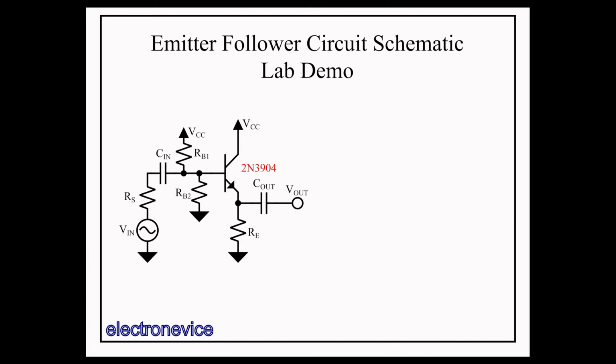Then the ADC converts the voltage on the capacitor over a period of time depending upon the ADC technology being used. What this does is cause short bursts of charge to be drawn from the signal source by the ADC, which will cause voltage drops due to the output impedance of the signal source. Most ADC chips don't have input buffers built in to separate the signal source from this sample and hold circuit.